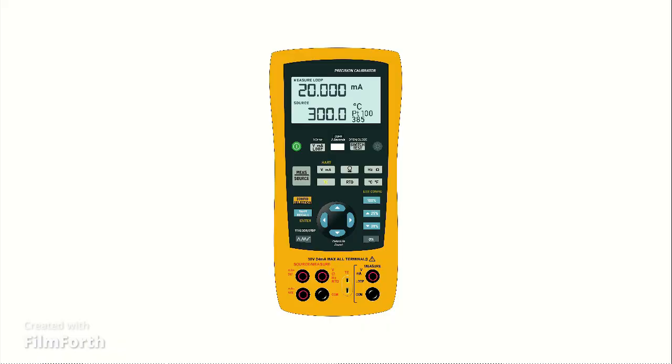This is a special type of instrument. It's called a calibrator. And one of the things it can do is measure and display the resistance of the RTD as well as its temperature. It can also simulate or mimic the operation of the RTD so that you can use the calibrator to test or adjust the instruments for correct operation. This is just some of the things calibrators can do, but we'll talk about them in a future video.